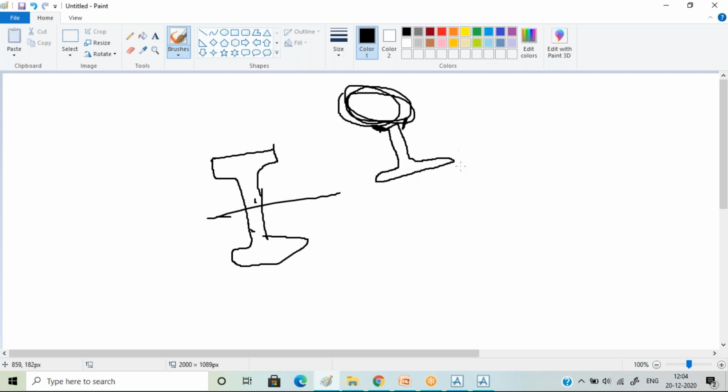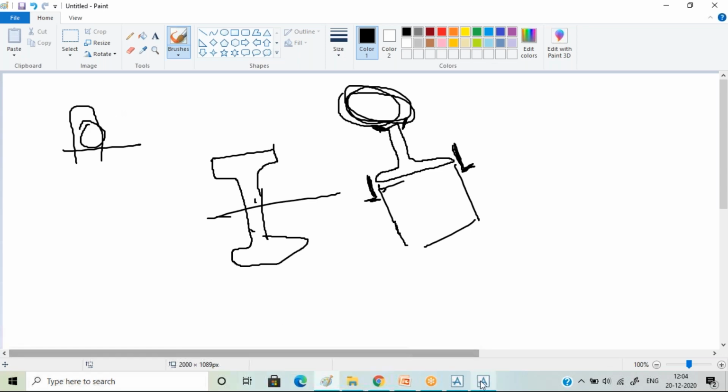Okay, now if you want to guide it, you can obviously place something over here. You can place either an angle or some plates over here, and this is your guided pipe. You can rest it on your beams, and this is how you're going to support your insulated pipe. And when you're coming to the supports for the non-insulated pipe, then they will rest directly onto your structural member, and if you want, you can U-bolt it. You can proceed like this. So this is the kind of supporting that you'll be going through.